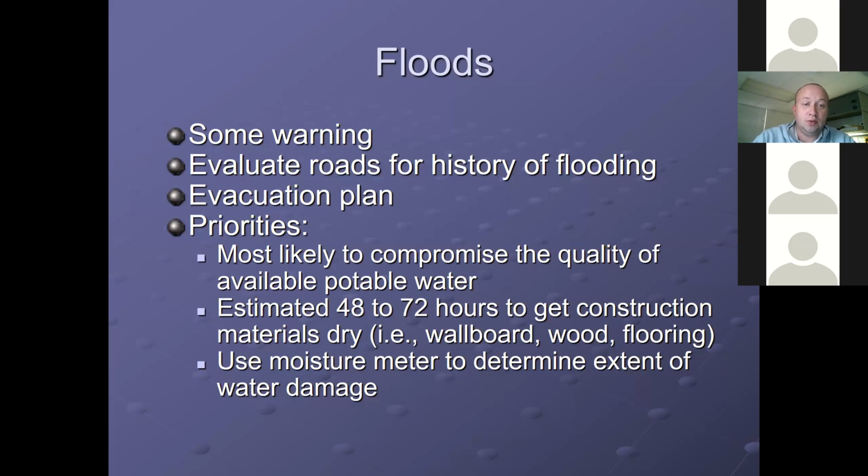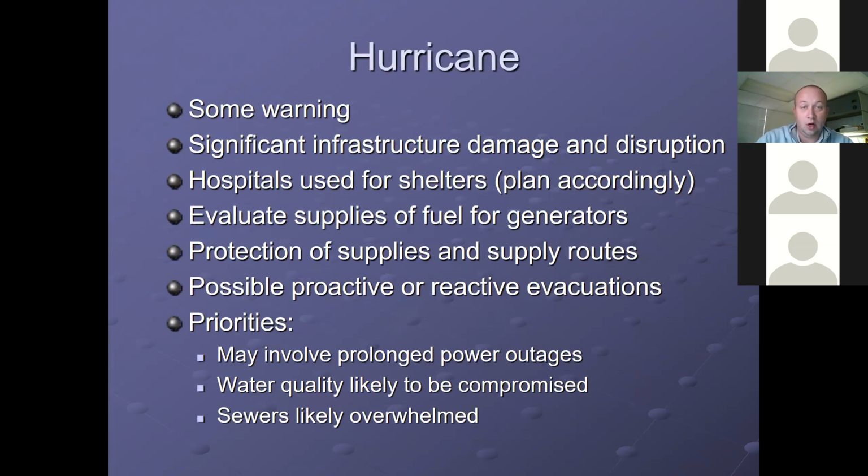When it comes to actual flooding inside of your building, it can take 48 to 72 hours to get construction material dry, and that's assuming you immediately start the drying process. Even once it's dry, it may not be salvageable. It may need to be ripped out, and that depends largely on the quality of the water and the relative humidity outside. Engage with your industrial hygienists and your plant engineers, your remediation contracting services. They can bring in moisture meters to really assess the extent of damage. It's important to remember that the damage doesn't stop at the water level. Oftentimes it extends beyond that.